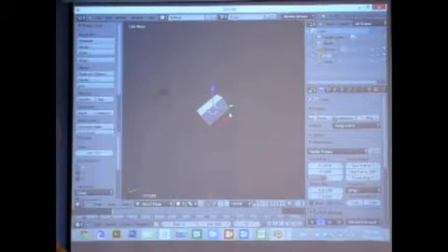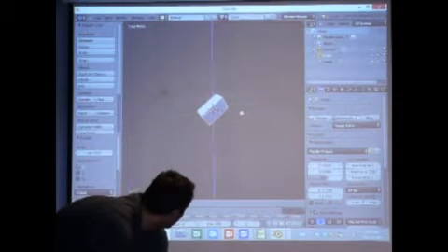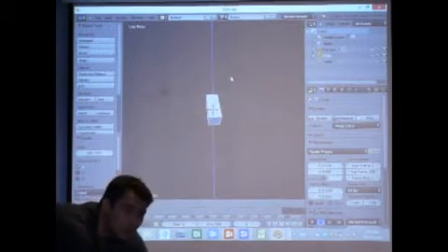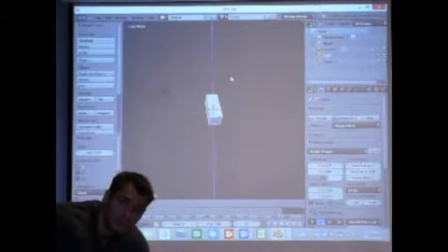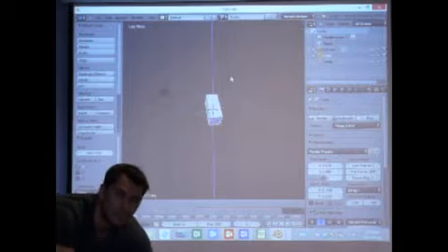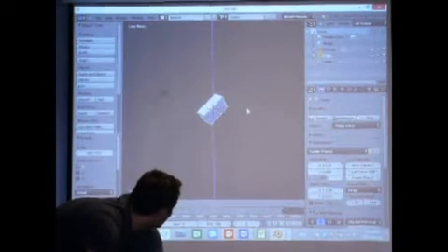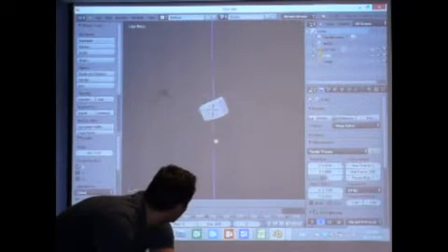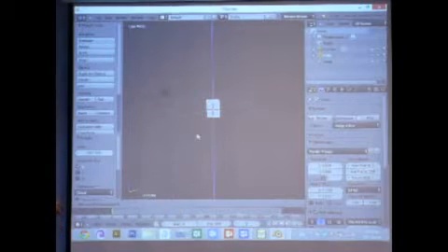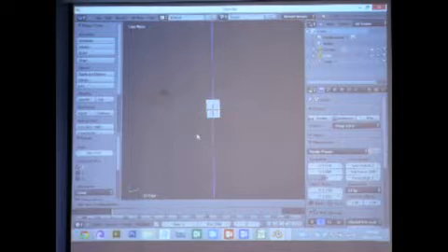Another important thing is that as it's rotating, say you press RZ, and you're rotating it along the z-axis, if you hold Control, it'll actually put in increments of 5 degrees, so you can get precision as far as 90-degree rotations, 45-degree rotations and 180-degree rotations. You can see it's actually a step-like rotation. You can see at the bottom left it shows you the exact rotation. So it says 245 degrees, and you want to do 180 or 90 degrees. Keep some symmetry.